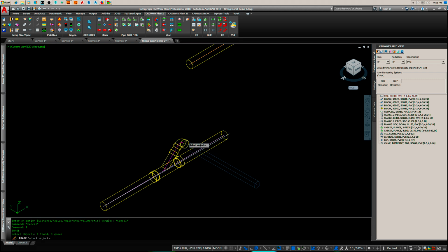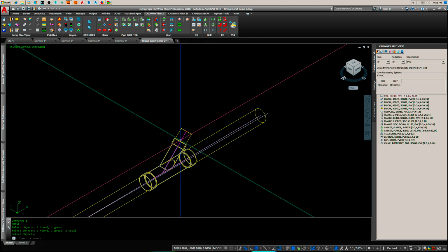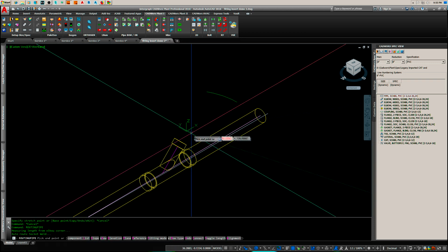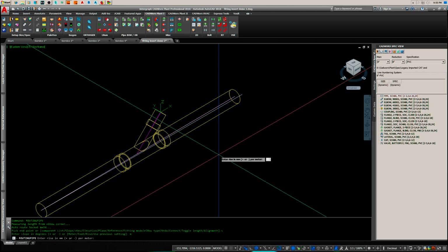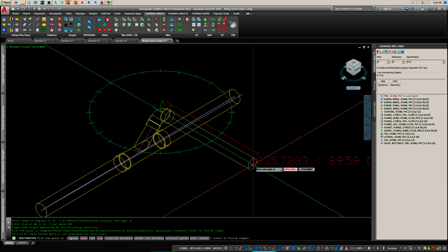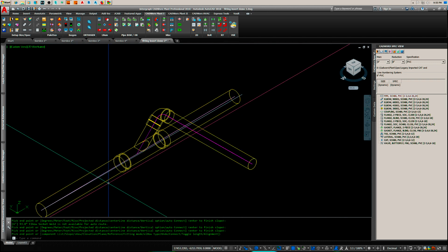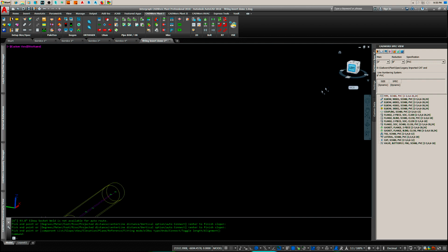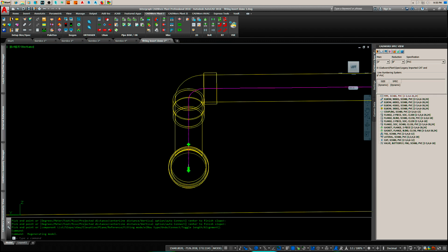Now, before I get into how to rotate these, this is a slope line, and we'll drag a slope fitting off here and we'll slope it 10, pick, enter, enter. All right, there's our slope. So let's look down the end of this. That fitting is in there perfectly vertical. This is sloped. This is a 90-degree fitting.